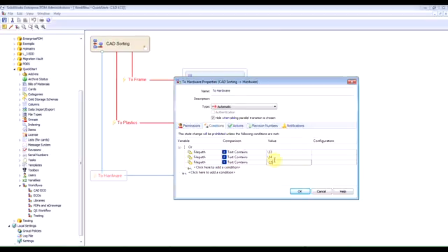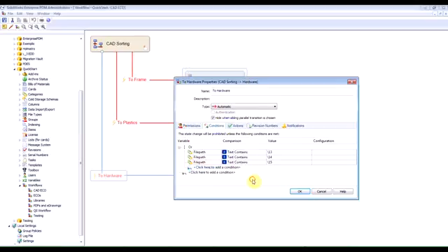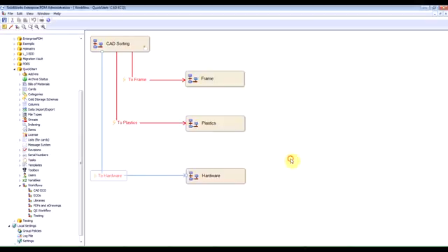So these conditions are just for the name of the file. You can have it for other things as well, whether it's for a variable that you have on your data card, or maybe a particular revision set, or even a category of file if files had a particular category. So it's all pretty customizable that you can use your sorting tool for. But in this case, we're going to do just the file name and the first 2 digits of the file. Hit OK. We'll go ahead and save this out. And we'll continue on here.